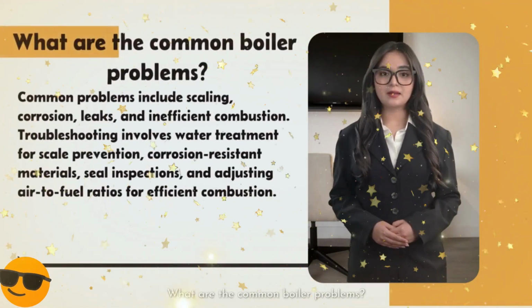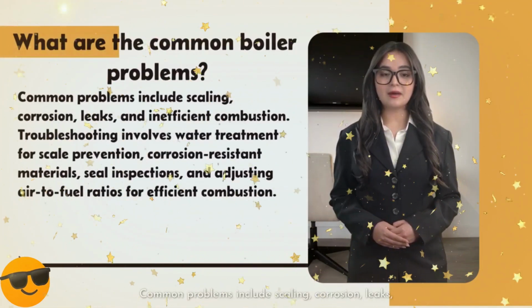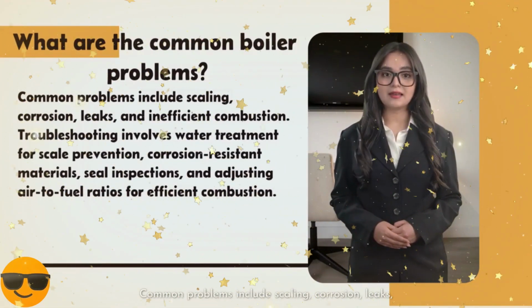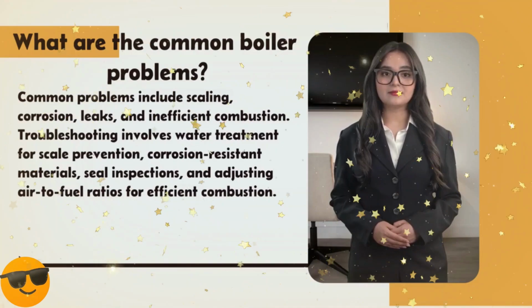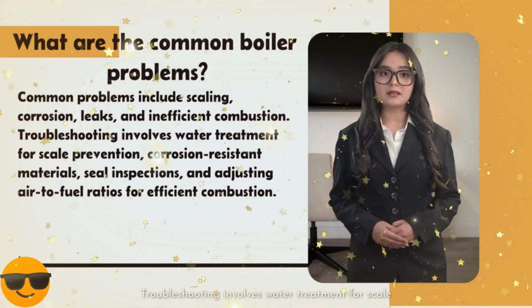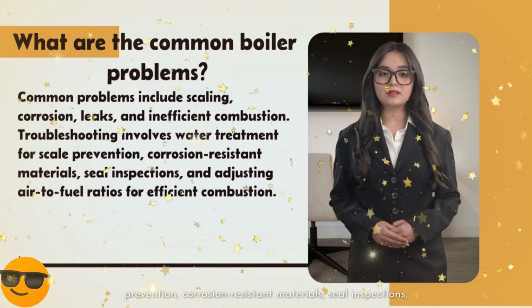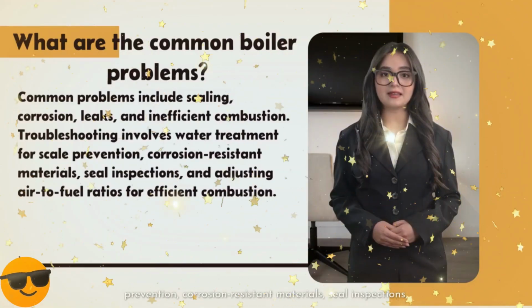What are the common boiler problems? Common problems include scaling, corrosion, leaks, and inefficient combustion. Troubleshooting involves water treatment for scale prevention, corrosion-resistant materials, and seal inspections.